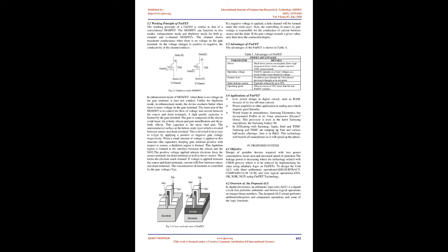In Jitendra Kanungo et al. [8], they analyzed the energy performance of a complete adiabatic circuit/system including the power clock generator, PCG, at the 90nm CMOS technology node. The energy performance in terms of the conversion efficiency of the PCG is extensively studied under variations of supply voltage, process corner, and the driver transistor's width. They proposed an energy-efficient single cycle control circuit based on a two-stage comparator for the synchronous charge recovery sinusoidal power clock generator, PCG. The proposed PCG is used to drive the 4-bit adiabatic ripple carry adder, RCA, and the simulation results are compared with the adiabatic RCA driven by the reported PCG.